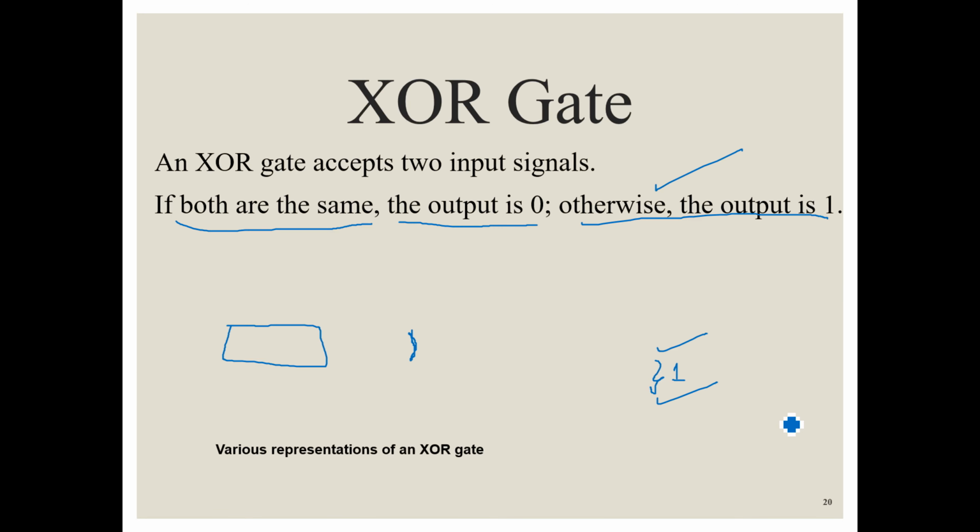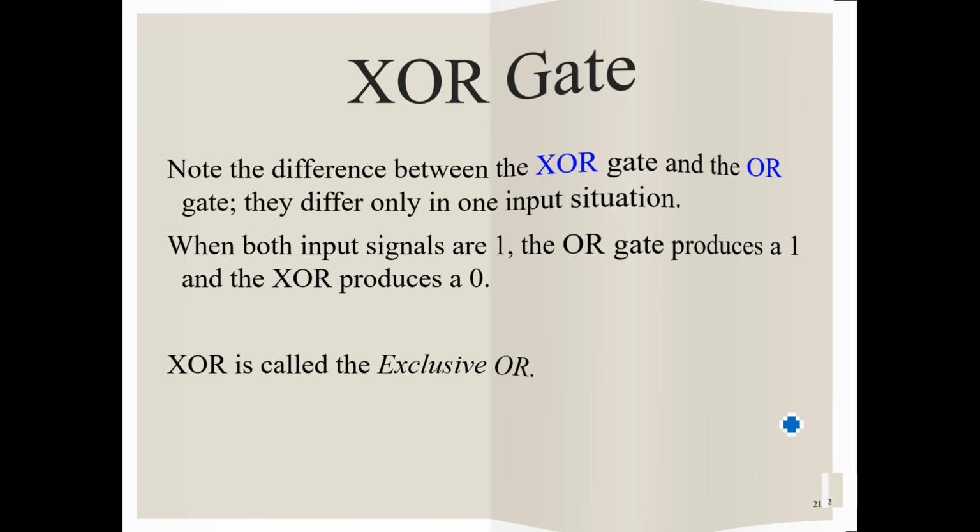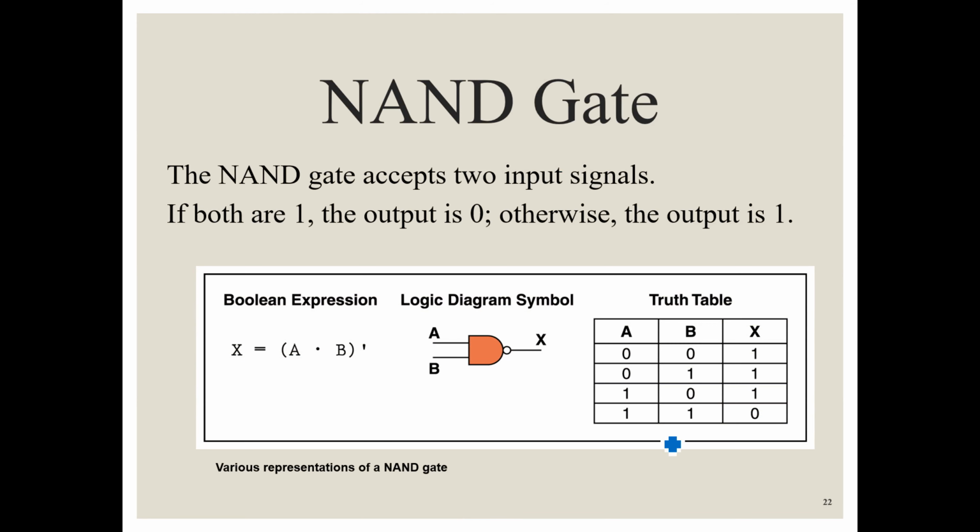So now let us see the NAND gate. See now the truth table. You can see that the entire output is different. In the previous case it was 0, 0, 0, 1, and here the difference is 1, 1, 1, 0. Exactly, it has complemented the entire thing. For the AND gate it was 0, 0, 0, 1. But the NAND gate is a NOT of AND gate, so that's why you have got 1, 1, 1, 0, exactly the opposite of these outputs.